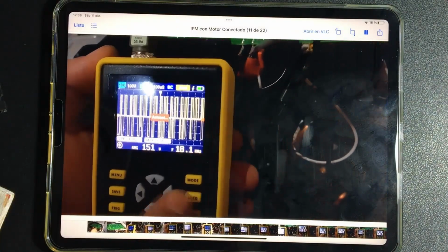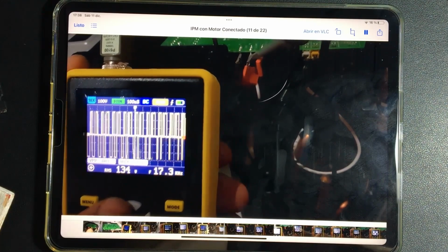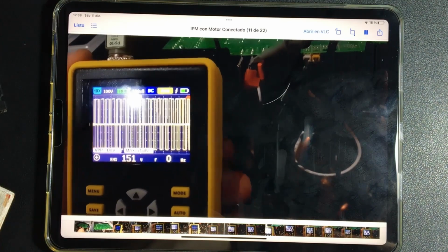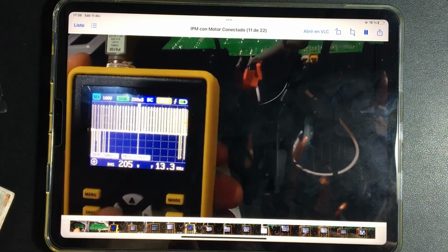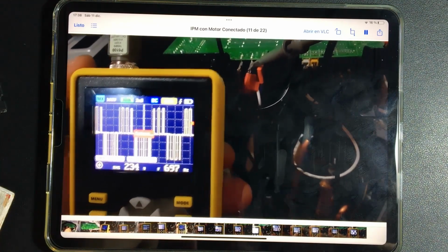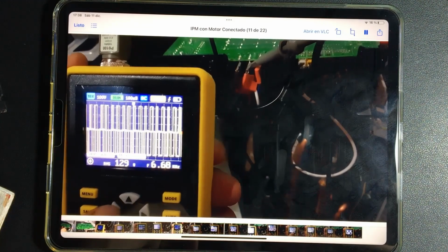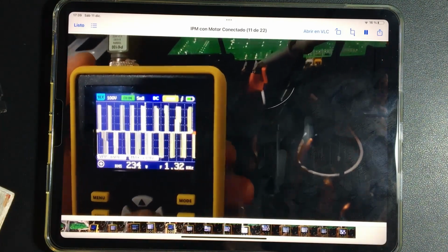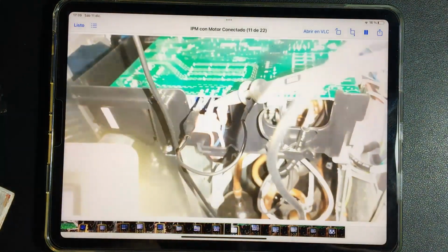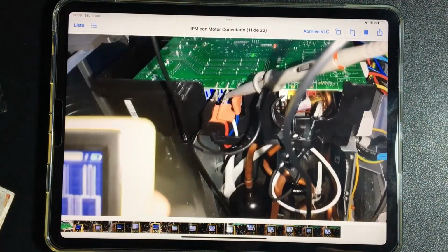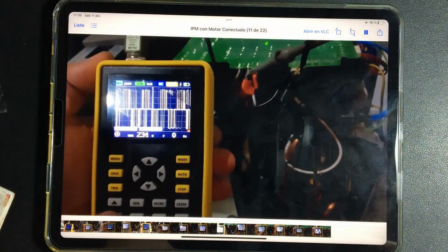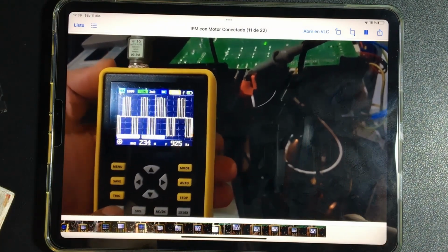It doesn't look good there, but we're going to press the automatic key and calibrate the time. And we're going to put it in a position where we can see and understand everything we were explaining. We're changing the time that the oscilloscope shows. It looks much better there. We're only seeing one phase, because this oscilloscope is only one channel. If we placed it in any of the other forms U, V, W, in any way, we would see the same, but at different times.